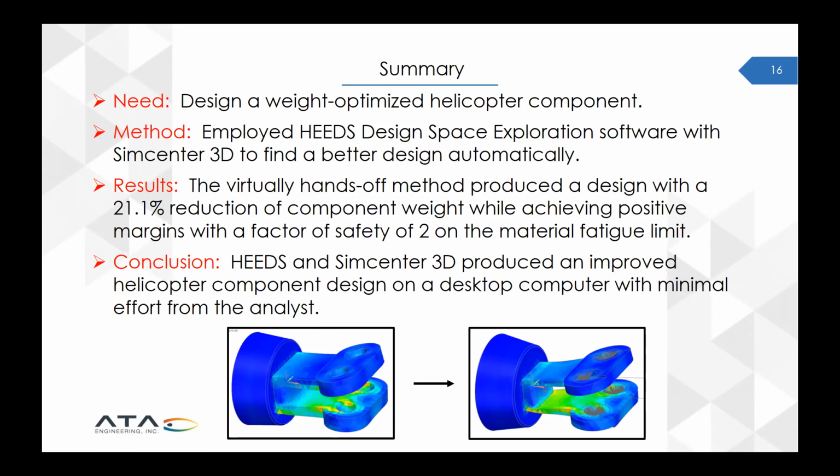But then I'm thinking that you also might be able to put mesh controls on a fillet radius or something. So maybe the concern is when it remeshes, maybe it won't know best practices of things like we want 3 elements across our fillets. So I imagine if you went into the FIM and you put that mesh control in, I think it would remember that across geometry updates and remeshes too, in which case that might help make sure that your element quality stays consistently high from run to run. Yeah, those are all the tricks of the trade that I've been trying.